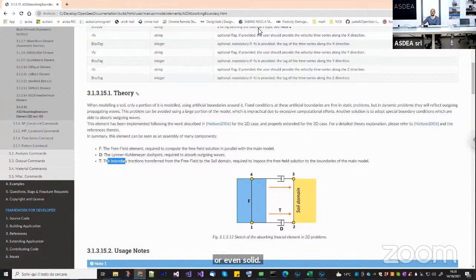So the point is this number times your unit system. If you're using meters, is 1e-4 meter small enough to be considered 0? In my opinion, if you're using meters, this one is probably too high. Typically when I use meters, I use 1e-6, and I can accept this one if you're modeling in millimeters. So as I told you, it's not important how large your model is. It is important the unit system you're using. Is it clear?